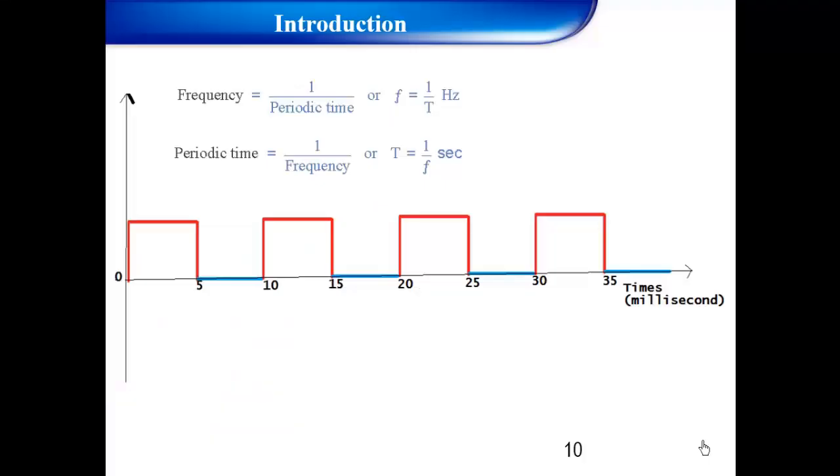Now like this: tone(pin 3, frequency 100, duration 40), I mean four periods. The pin is 3 for example, and frequency 100, I mean 5 milliseconds on and 5 milliseconds off.